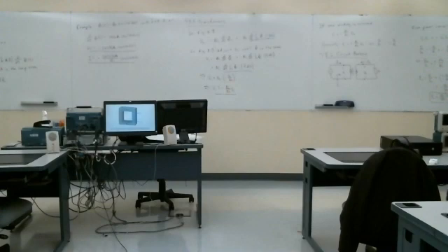If it's capacitive, it still looks like a capacitance, but it's multiplied by the turns ratio squared. So if it's what's called a step-up transformer, where N2 is greater than N1, then the impedance looking into the primary is smaller than the load impedance. We see a smaller load impedance.